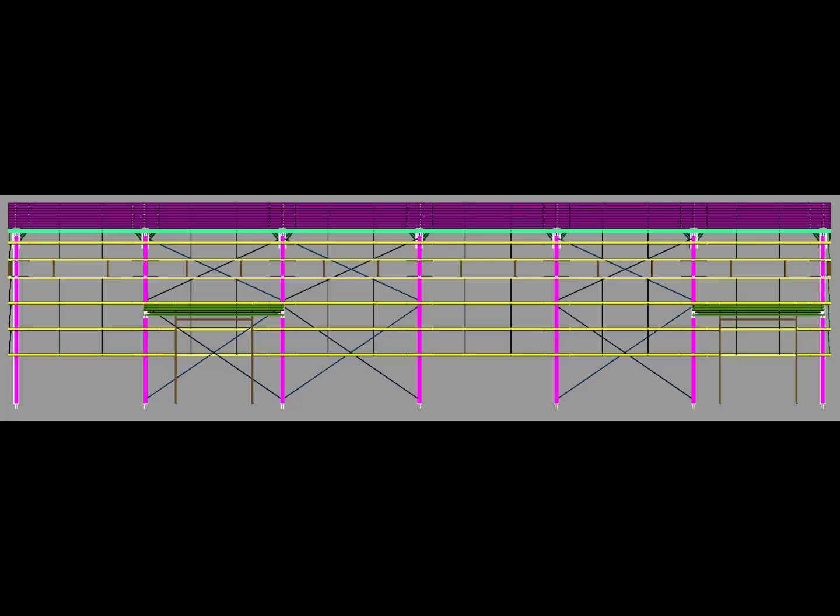This is the main purpose of studying a real project. We are not simply learning individual member names. We are learning how those members work together as one structural system. Now let's focus again on the side wall sag rod. Its importance comes from the fact that the side wall secondary members can have significant unsupported lengths. Providing appropriate intermediate restraint helps the secondary framing system behave properly. The sag rod therefore becomes part of the overall secondary framing arrangement.